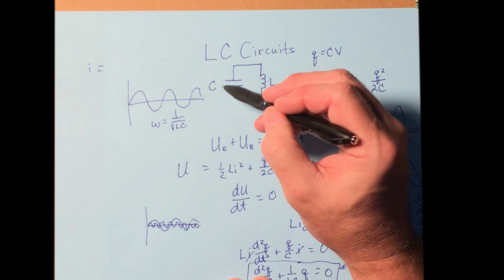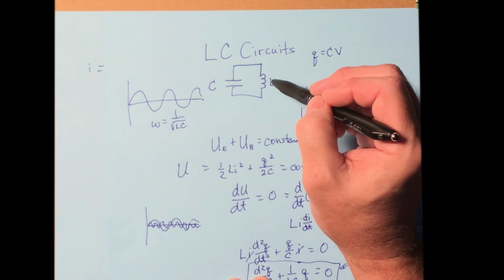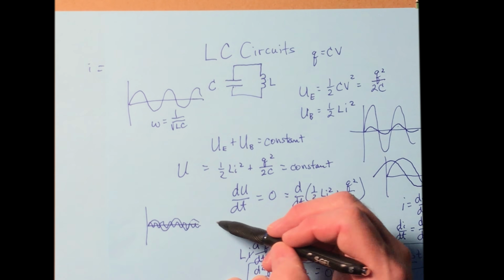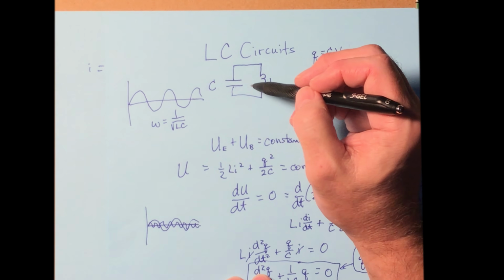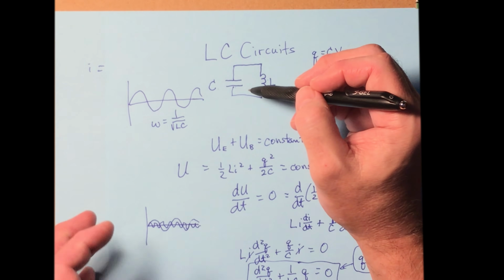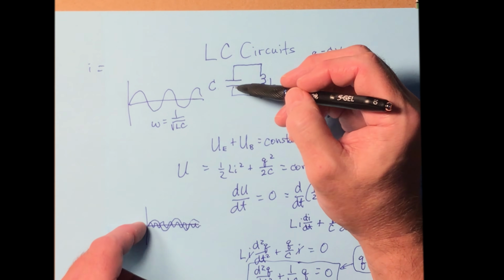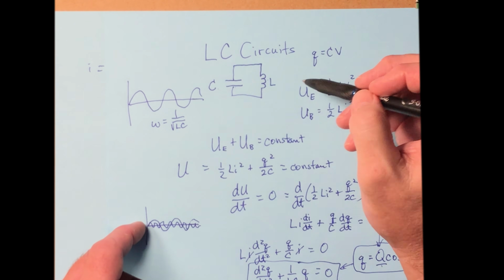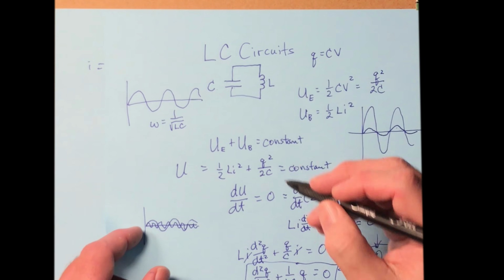So when you build this circuit, it's the L and the C values that you choose that determine how quickly it varies, either slowly or fast. All right. So those LC values then are the thing that cause the oscillation. Remember, in RL and RC circuits, there was no oscillation. It was straight decay or rise and level off. Here with L and C together, we have an oscillation.